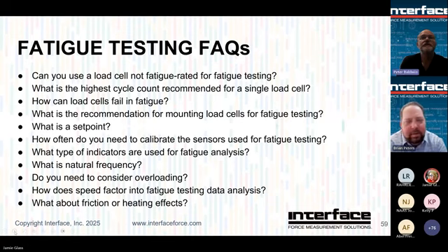How can load cells fail in fatigue? Well, the most common way we see them fail is due to unknown off-axis loading. So do everything you can to isolate best you can. If you've got some concerns going up a little bit in capacity, usually not a bad option. Again, as long as you can handle the inertia, the mass, the dimension, just want to make sure that you can tolerate. You just really don't want to get 9 months into a 10-month test and have a failure.